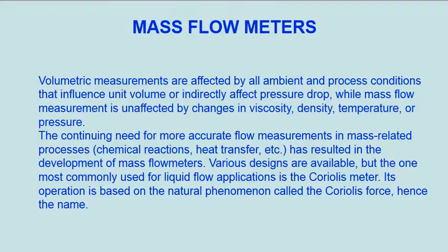Volumetric measurements are affected by all ambient and process conditions that influence unit volume or indirectly affect pressure drop, while mass flow measurement is unaffected by changes in viscosity, density, temperature, or pressure. The continuing need for more accurate flow measurements in mass-related processes, chemical reactions, heat transfer, etc., has resulted in the development of mass flow meters.